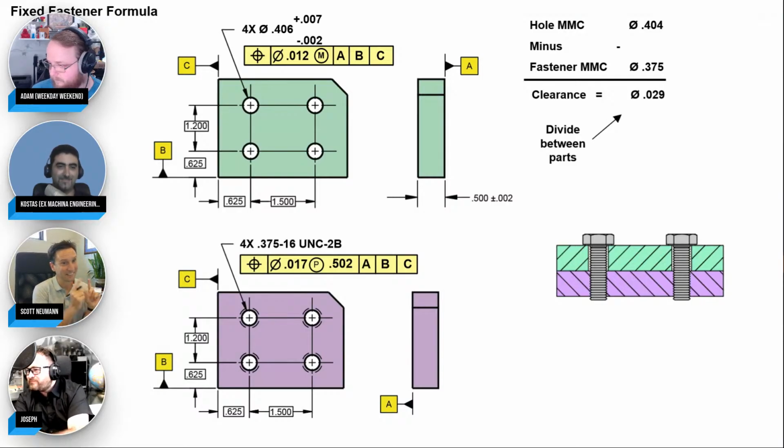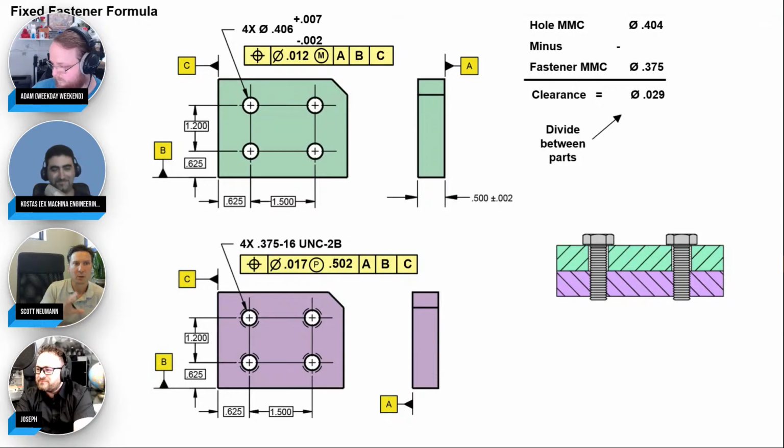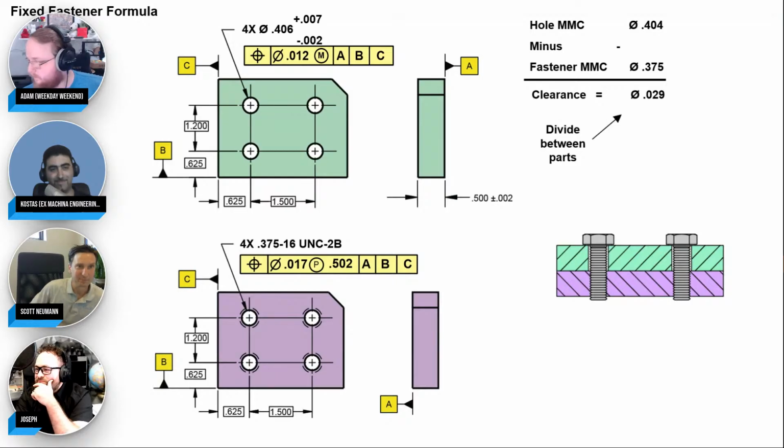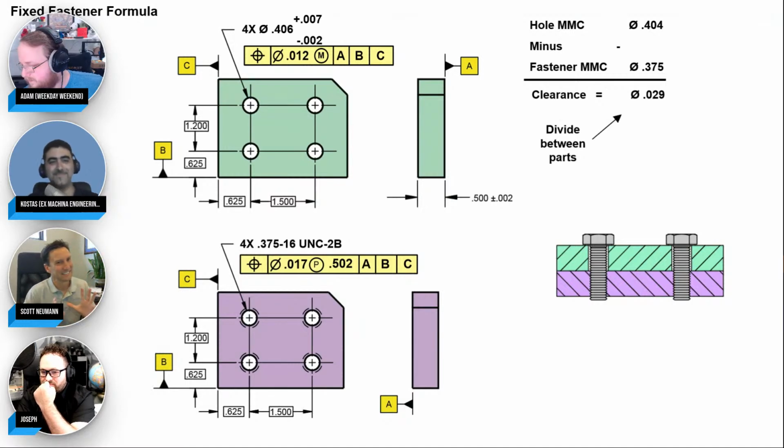But I'm not changing my drawing, because the next person wants to use the thread gauge and do it properly. So I want to give them the full 17 possible. What I say is that's a quality plan, and we guard band tolerances. Guard banding is where you artificially reduce the tolerance to protect your hard boundaries set by the drawing. So you're guard banding those tolerances, and cool, you do that for now. But as soon as we get an upgraded CMM, then we're going to the full function. And then I don't have to go back to the design engineer and ask, hey, can we get that 17 back on the function again? Sorry, that ship has sailed. We're back at 15. So yeah, I really like to stay functional. And then quality, yeah, you do your thing.